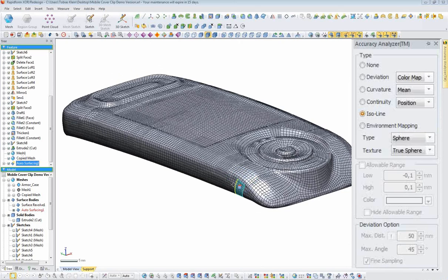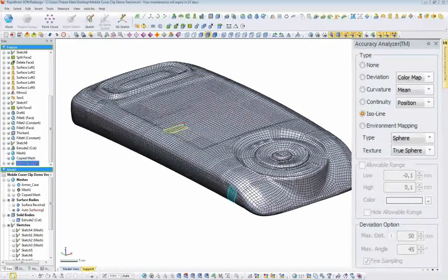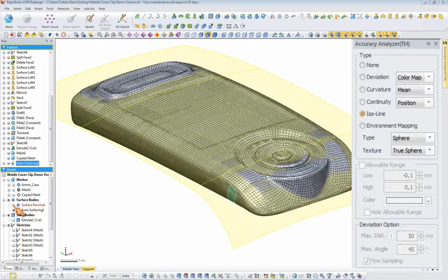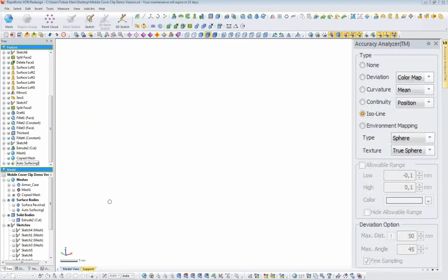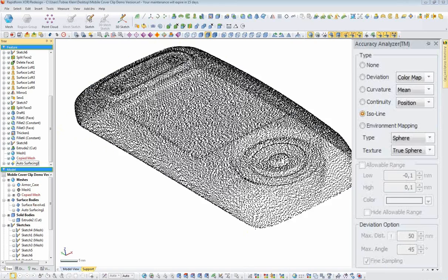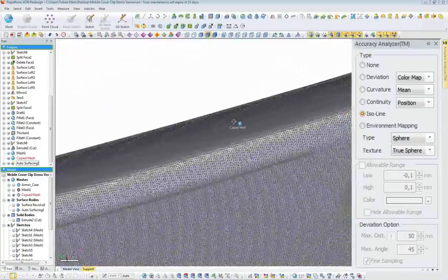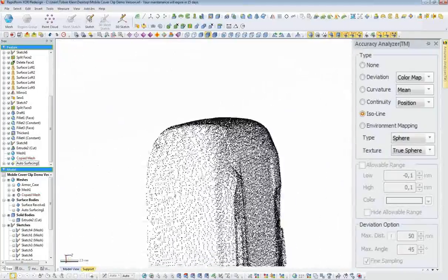This surface can be exported to STL as well, but why are we going this way around that surface? We can use the scan directly. If we close the scan already, then we don't need this surfacing, and we can use the scan directly and export this to STL. It's also a mesh which can be exported to STL. However, it has no thickness, so it cannot be printed directly.